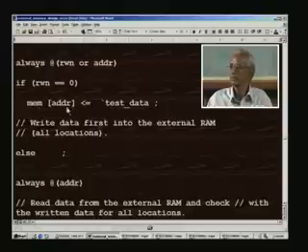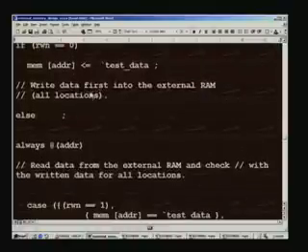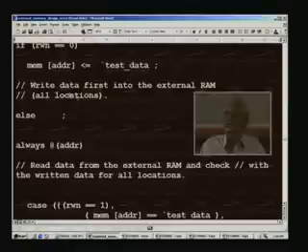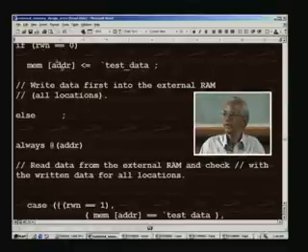and to this particular location addressed by the controller will be written the data test pattern, namely 555, into the RAM here in the test bench. Write data first into the external RAM, all locations. So, what we do is we write all 555s in every location. There are 65,535 locations, all locations it will write the same data in the first phase and then change this RWN and